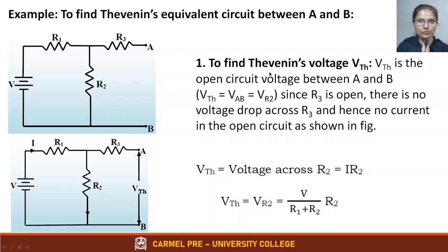What should we do? We have to open circuit this and measure voltage across this. That's all. That is our VThevenin. That is easy if you have a multimeter with you. But theoretically, what to do? You have to analyze the circuit now.